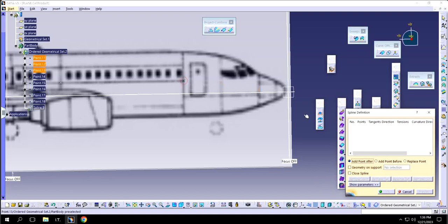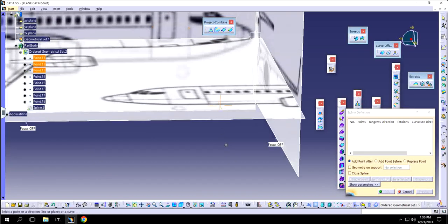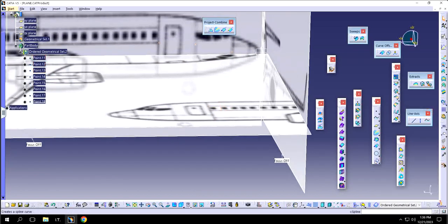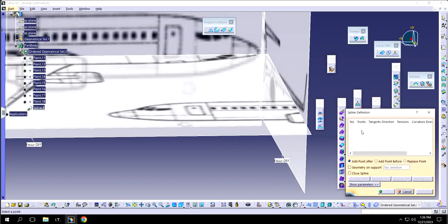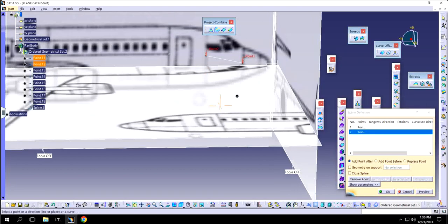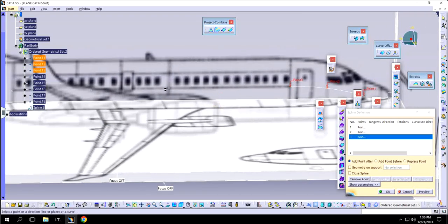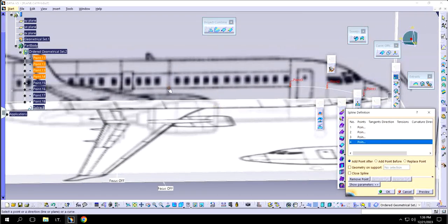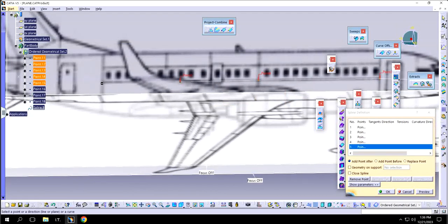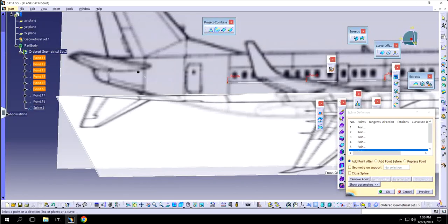And if I try to click, oh, my bad, spline, start clicking on spline right here. This point right here, this point here, right here. Similarly, I'm just going to join all the points so that it becomes one continuous line or a guiding curve that I can use for making my adaptive sweep feature activate.